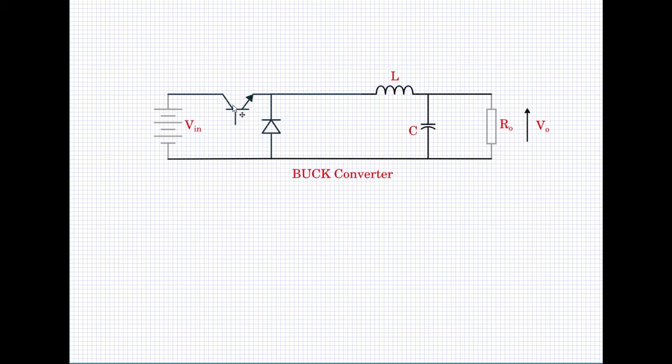Now this is the buck converter. We have put the switch on the positive arm of the supply. We can as well put the switch on the negative or the return path of the current without affecting the operation of this whole buck converter circuit. So let us do that. For example, let me move this down and let me move this up.